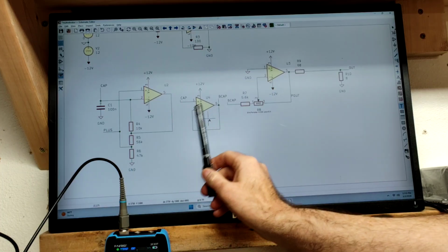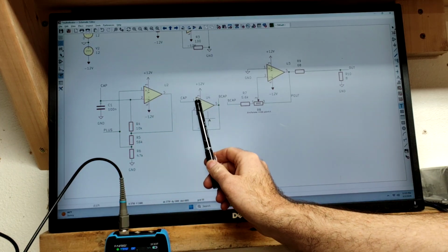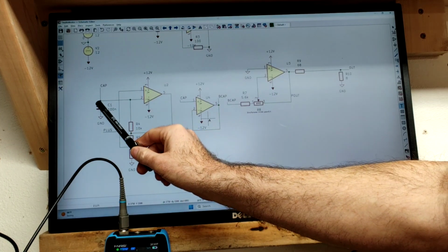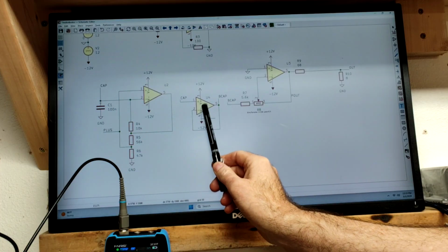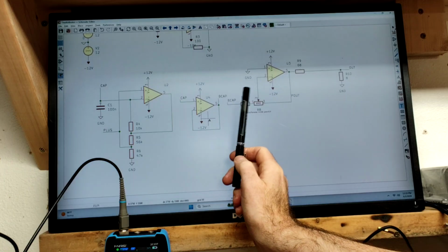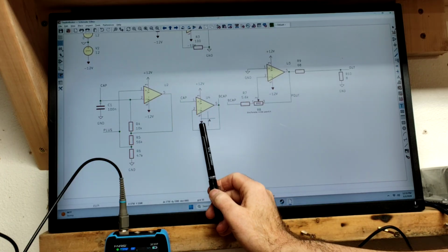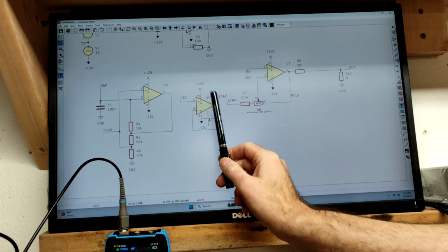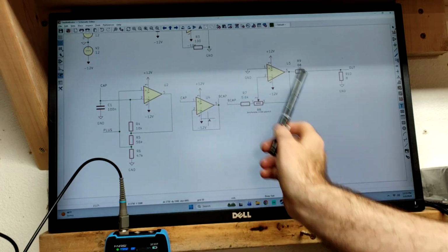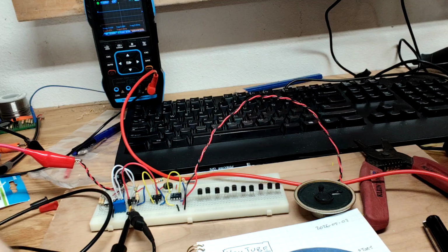And so it's just exactly following whatever's there. And now we have high impedance here, meaning that no current is going to flow from this capacitor into this op amp. If it's an ideal op amp, zero current flows in there. In practice, it's almost like a mega ohm resistor or something on that order of magnitude. And then its output is what we put into our amplifier. So let's fix the circuit and see how that sounds.